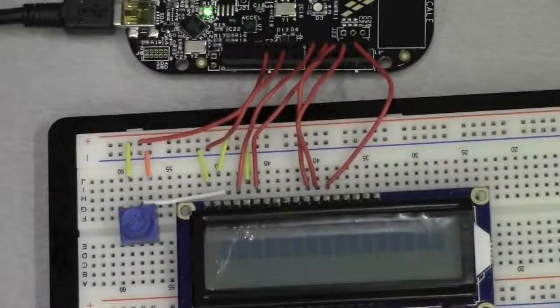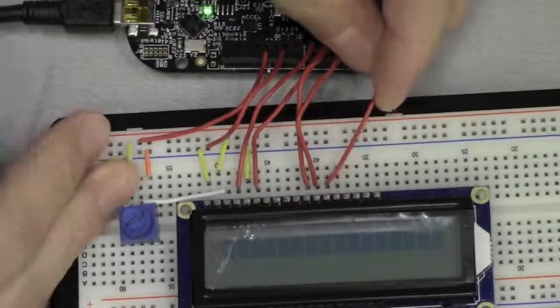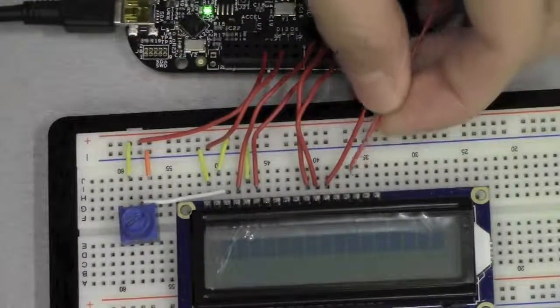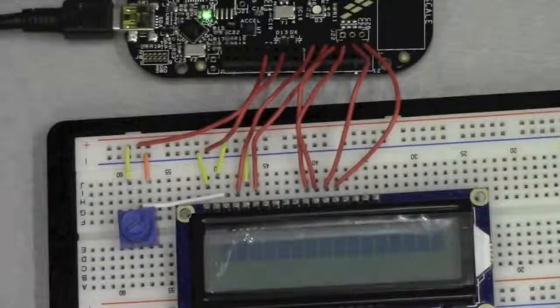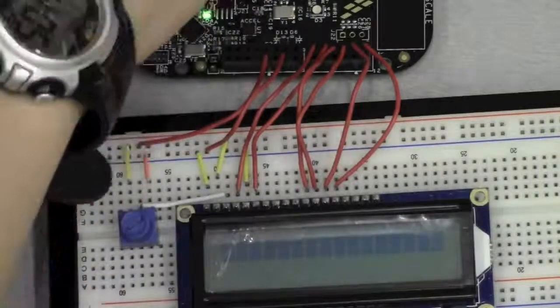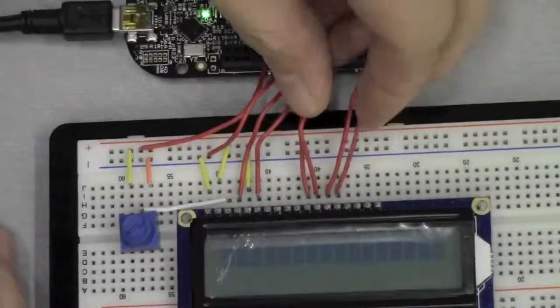And then we need just one last wire, and that should do it for at least the basic programming of the LCD display. Again, there's additional ones on this for backlight, but I'm not going to be too worried about it. For the sake of just proving that it works, I'm just going to connect pin 15 on this, which is the power supply for the LEDs, to the 5-volt line.